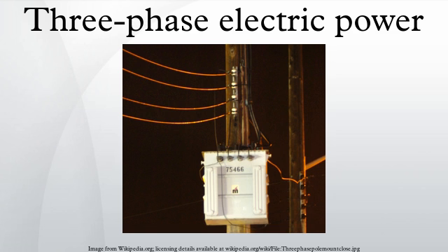Zigzag transformers may make the equivalent of 6-phase full-wave rectification, 12 pulses per cycle, and this method is occasionally employed to reduce the cost of the filtering components, while improving the quality of the resulting DC. One example of a 3-phase load is the electric arc furnace used in steelmaking and in refining of ores. In Germany, a 1965 publication shows some full-size stoves are designed for a 3-phase feed. However, the individual heating units may be connected between phase and neutral to allow for connection by 3 individual circuits on the same single-phase supply.